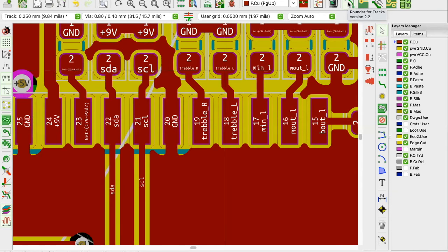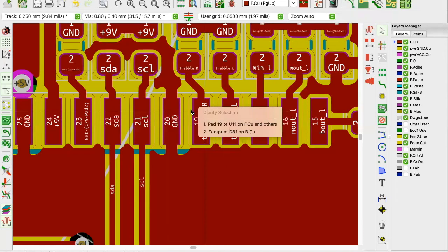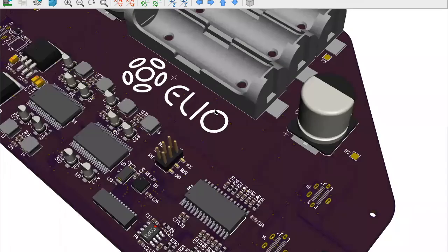That had us changing the pad sizes so that the solder mask could easily flow, because the fab house will tell you, if you don't do solder mask here, we cannot assure you that you won't get a short in these pads. So it plays a very critical role. It's very important that you check with your fab houses what their limits are in terms of solder mask and how it can flow when you have such pads.